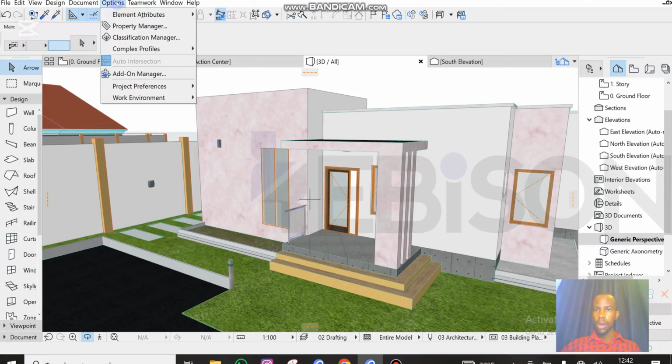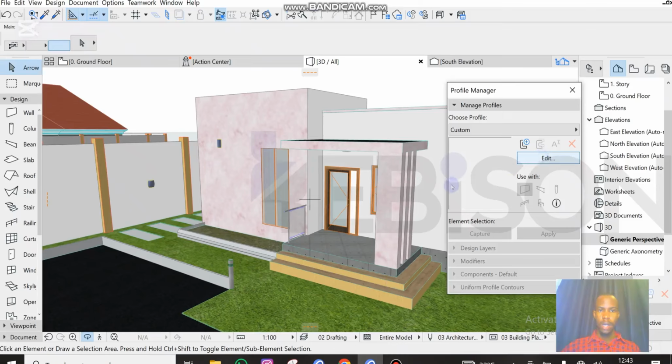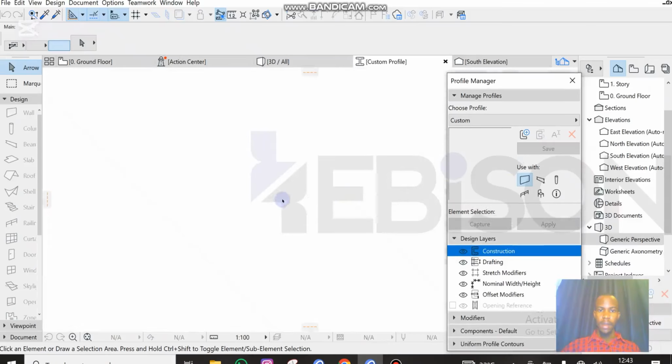You come to your options, your complex profile, and you edit. The height of a curve can't be more than 300, depending on the capacity of what is to partition. If the partition is a very high density road, you need to increase the height of the curves because of the heavy duty trailers or trucks that are to pass the road.